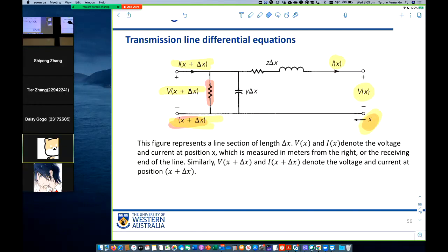And then we have the series impedance on the horizontal line of the pi circuit, right? We see that. So we have a resistor and we have an inductor there. Let me show that. So this is the resistor and the inductor we are looking at, right? And then we have the shunt capacitor, which is this term here, right? Now, this Z here is the impedance per meter.